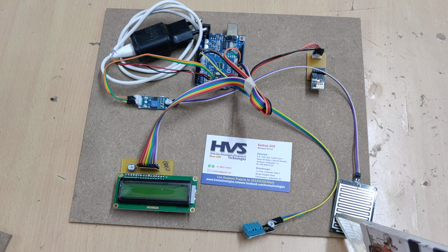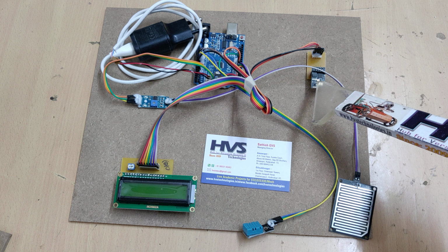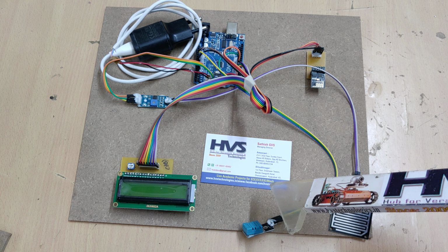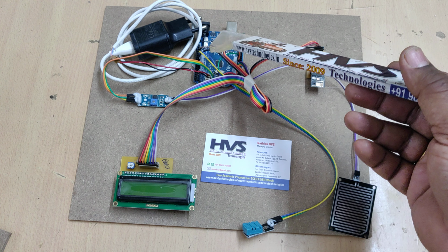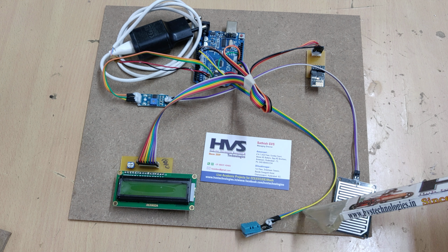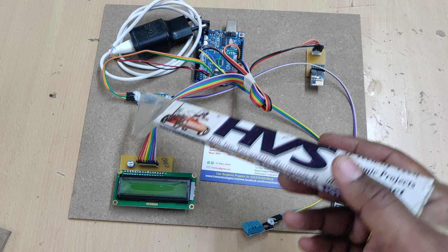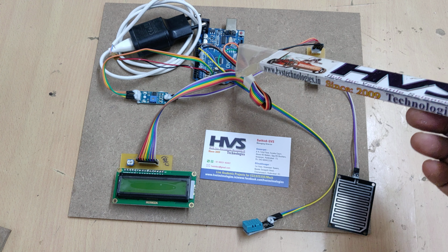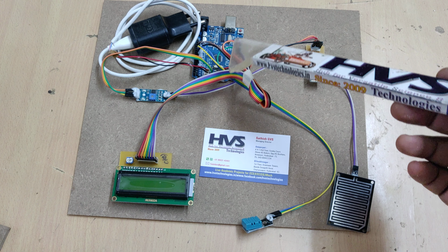These three sensor values are continuously monitored on this 16x2 LCD screen, and the same data will be uploaded to the ThingSpeak cloud platform with the help of this ESP8266 Wi-Fi module. The operation of the input sensors, reading, and output controlling modules is done with the help of the Arduino UNO board, which takes the input from the DHT11 at pin number 10, and the rain sensor at pin number A0, and the LCD module as output connected at pins 22 and 7, and the ESP8266 Wi-Fi module is connected at pins 8 and 9.